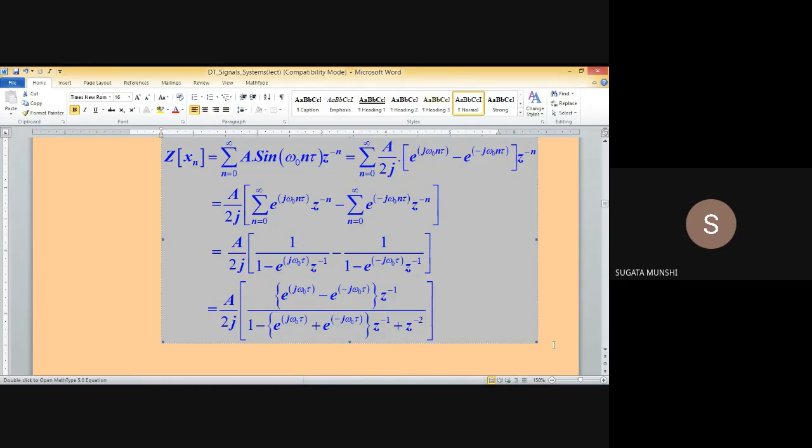You will see later, if you treat the case of inverse z transformation, that means for a given X(z), if you want to get back the original time domain sequence x[n], in absence of knowledge of the ROC of X(z), you cannot do that uniquely. There will be ambiguity.